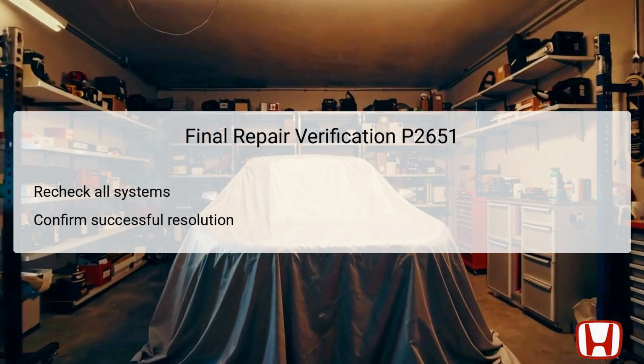It's advisable to run the engine for a short period and observe whether any warning lights, specifically the check engine light, reappear. Utilization of the HDS to perform a self-diagnostic check after repair can confirm whether DTC P2651 or related codes return.